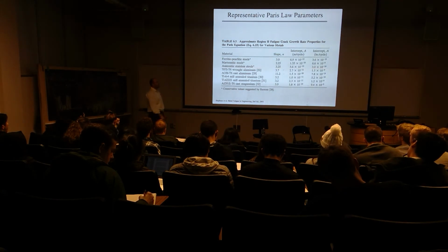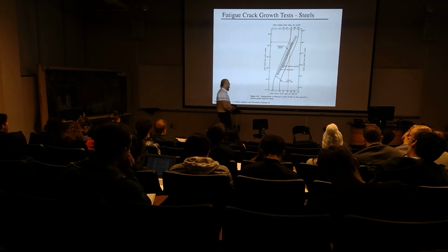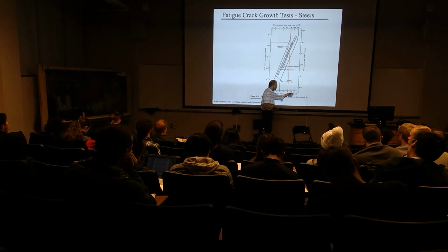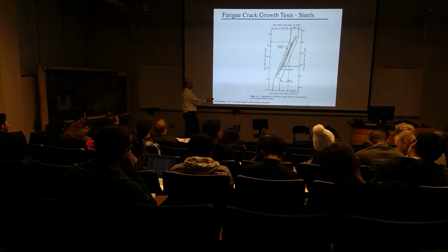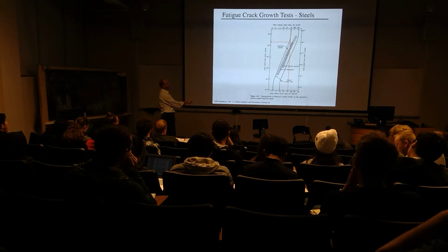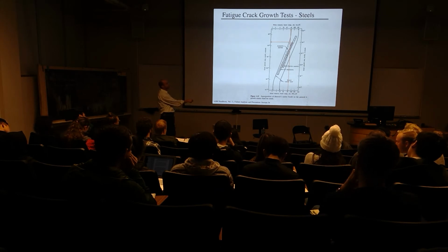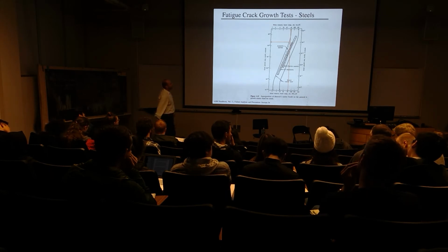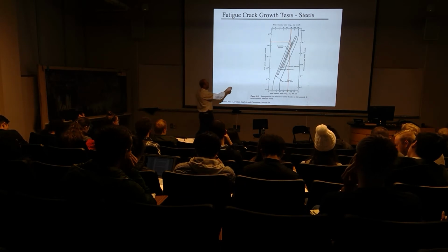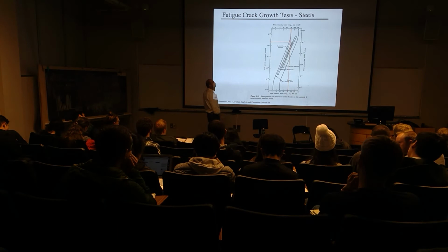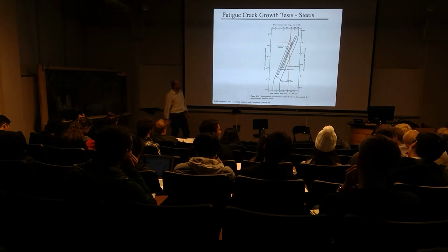And then in that example that we develop, I end up showing you an estimate for delta K that's about 55 megapascal square root meters. And I look and I say, where does that actually end up in terms of the austenitic stainless steel responses? It's right here. It's at the end of the stable portions of cyclic crack growth. So there's my value of 2.7, like I said, or 2.69. It actually agrees very well with what Barsom's estimated dA/dN value would be.